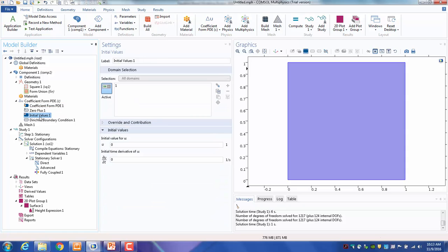In a time-dependent problem, those are physically meaningful quantities of where you are starting, what was the state of your problem at t is equal to 0 or whenever you start solving this problem. But for a stationary problem, they don't have any physical meaning. But can you think of a way they can be useful? Any guess? Yeah. Can you elaborate more? Convergence and nonlinear iterations. Exactly.